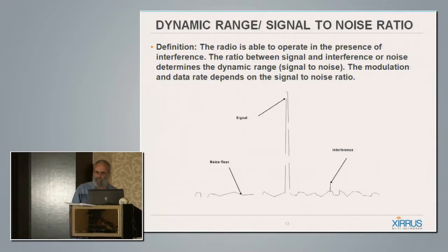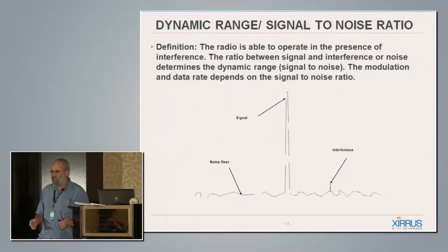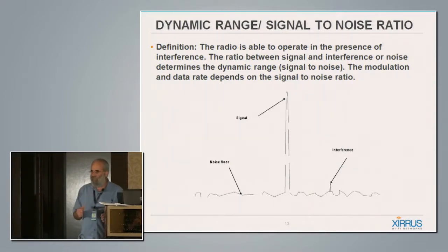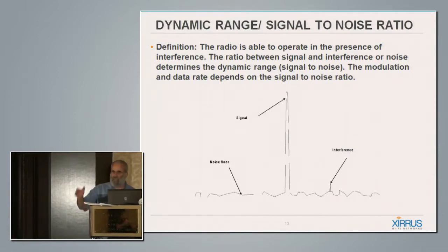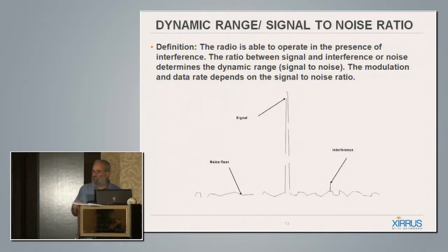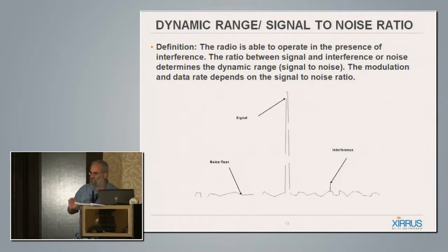So it's very forgiving. But as we move to much higher speeds and higher modulation schemes, things need to be just perfect. So the signal to noise might be 20 dB. So the RF link needs to be tuned as perfectly as possible. Everything needs to be linear, with minimal distortions.